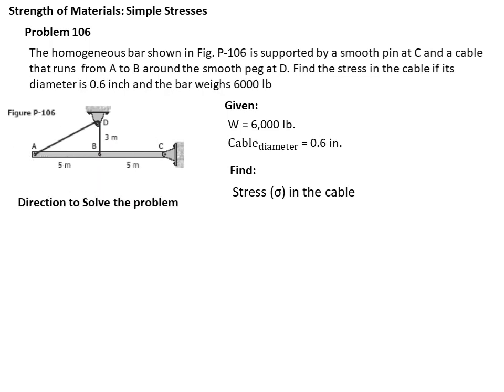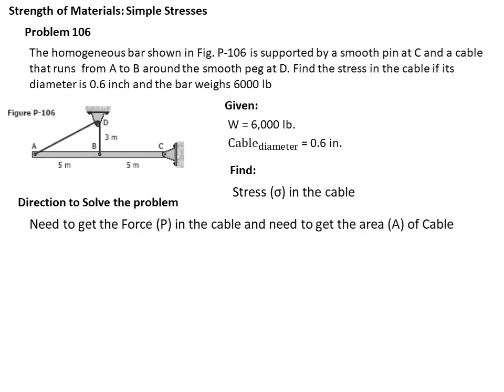Okay, so this is the direction on how to solve the problem. Need to get the force P in the cable and need to get the area of the cable. Since we are required to solve the stress, we need the P and the A, the force and the area of the cable.